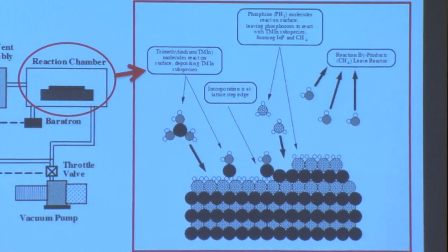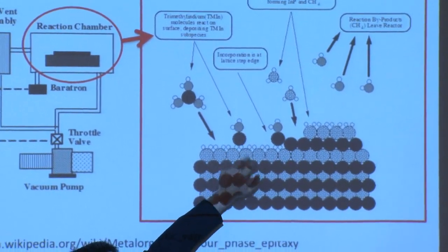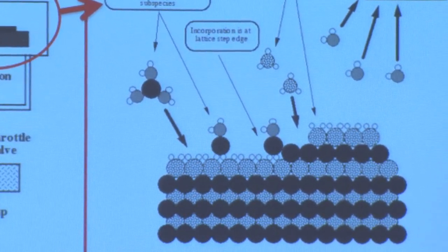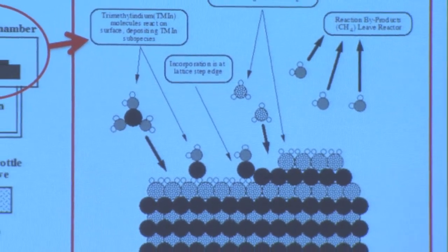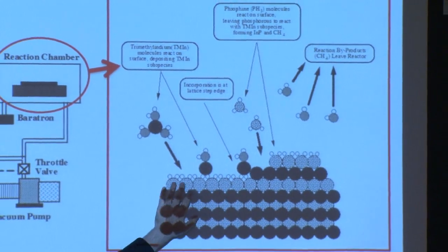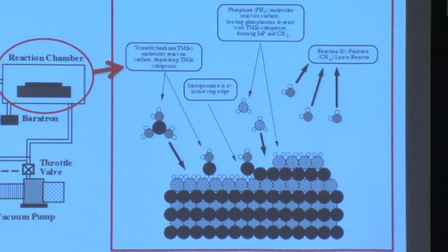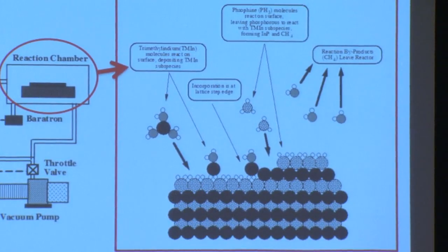This represents right here the separation, where we have the indium atom shown in black right here. And then the methyl groups are moving off, and essentially those will be sucked out of the chamber, leaving behind, in this particular case, a layer of indium forming, probably on another layer of material underneath, say, for example, your other species comprising the thin film, maybe phosphorus, so it would be indium phosphide growth.